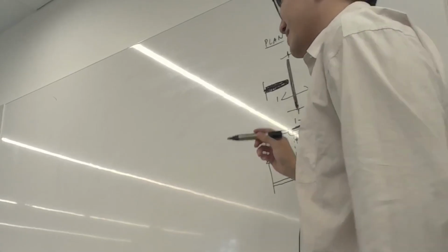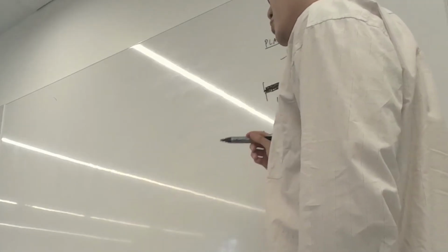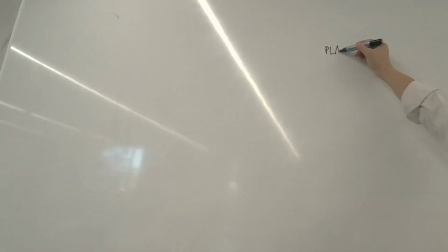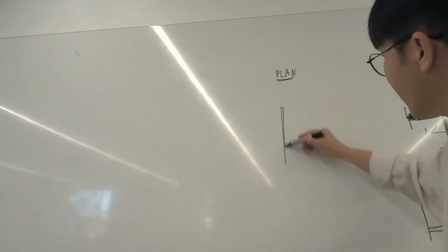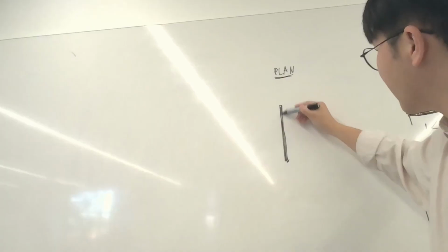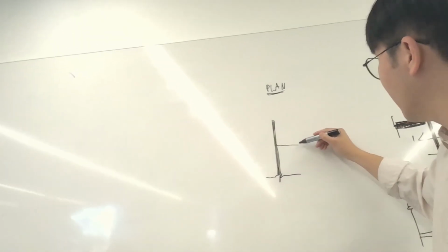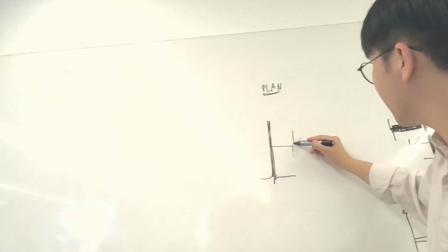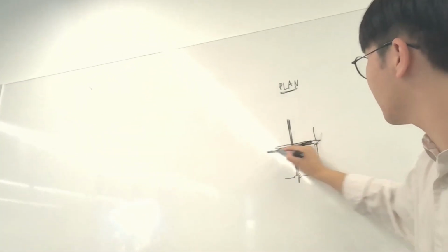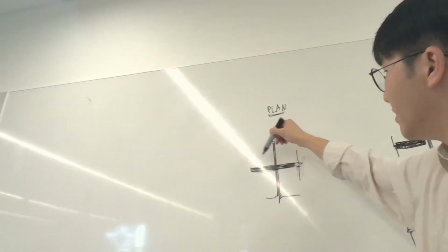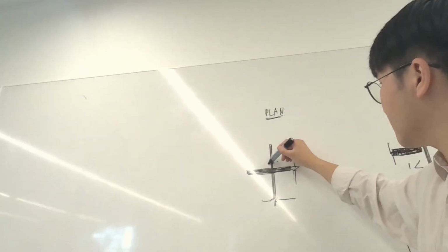Okay. So what I'm going to challenge you guys to do is think about what a moment connection looks like. I'll give you an example. In plan view, let's just say you have a cantilever. So that's a break line, that's another break line, that way. Plan view is top down. Yep, this is top down. Okay, so that's cantilevering. Therefore, there needs to be a moment connection here.